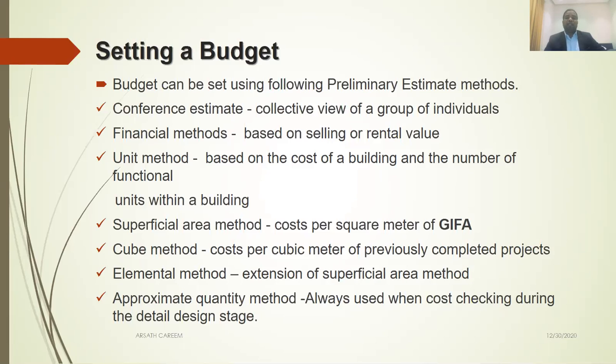Because they want to build a similar building. When you go to these shopping malls, they are all very similar to each other, so they can easily decide the cost per unit. Let's say 10,000 per square meter in Qatar, including all interior fit-out; we want to build 10,000 square meters at this much cost, then they decide.